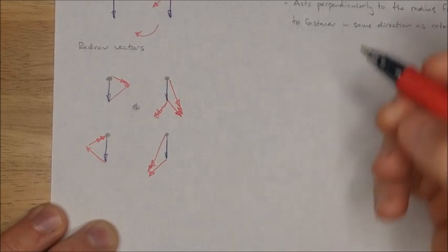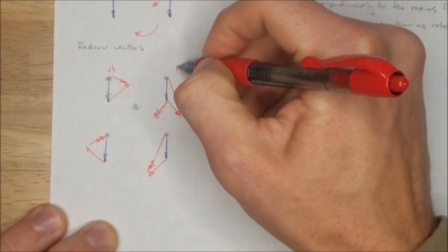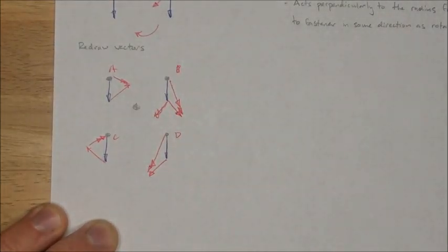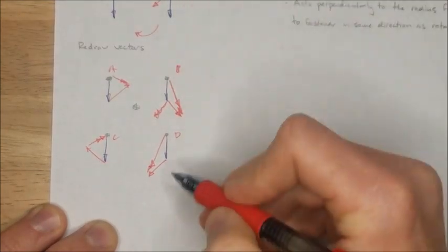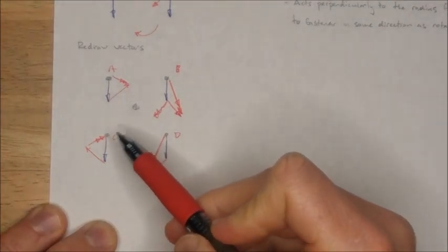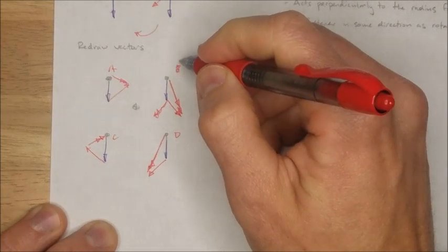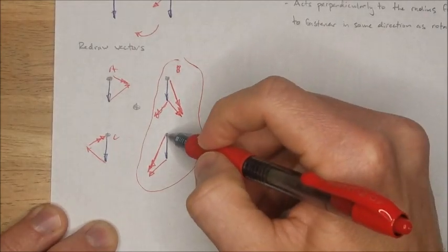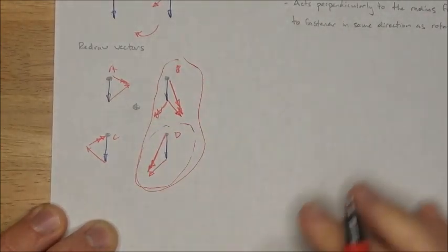So we can immediately see that the resultant vectors for bolts B and D are noticeably longer and greater magnitude than for A and C. So we know that we've got either B or D as our critical fastener. For the sake of this problem, we're just going to choose D as our critical fastener.